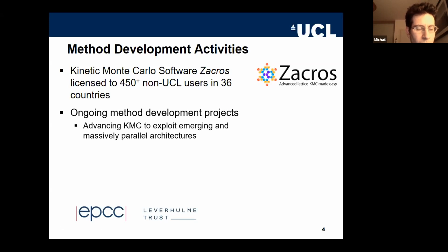So one of the most recent projects on the methodology development and software development has to do with the implementation of the so-called time warp algorithm, in which we break a large domain into subdomains. Each of the subdomains is assigned to an MPI processor, and then all of the processors have to communicate with each other to solve the problem. It is highly non-trivial because this decomposition can lead to causality paradoxes. And of course, there have to be some rollbacks and resimulations and certain communications that will resolve these causality paradoxes.